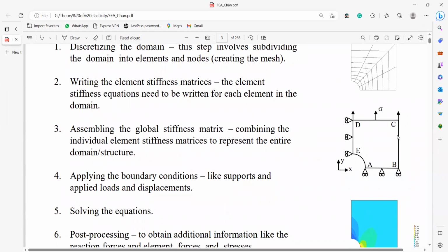So one end has to be fixed, and at the other end you can apply displacement or force. So now the boundary conditions are that it is fixed at one end and pulled or pushed at the other end. Now you have the global stiffness matrix and you apply the boundary conditions. What about the material? Yes, all the element stiffness matrices have the material properties as well.